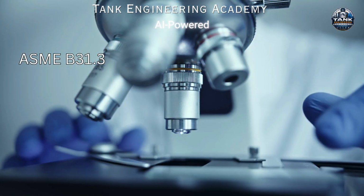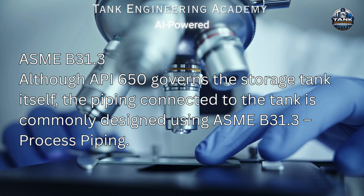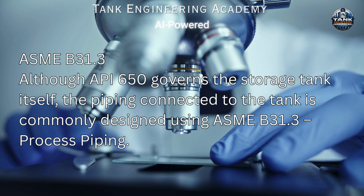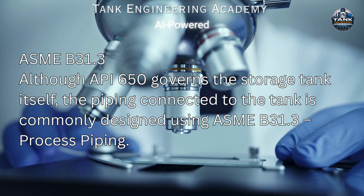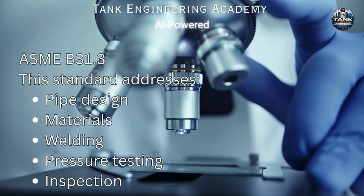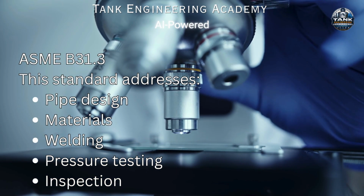ASME B31.3. Although API 650 governs the storage tank itself, the piping connected to the tank is commonly designed using ASME B31.3 process piping. This standard addresses pipe design, materials, welding, pressure testing, inspection.